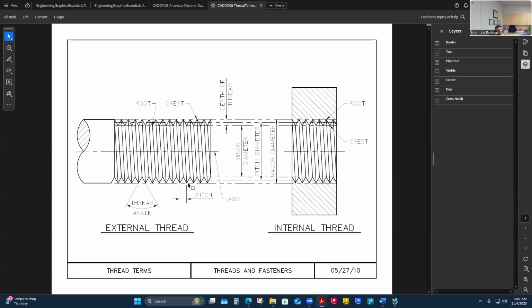The reason why I might need to know this is if I'm looking to design a round fastener, or if I'm redesigning something and I've got some equipment that I'm working with, I need to identify what the fasteners are that are being used so I don't detail them out wrong. So I might have to grab a fastener, grab my calipers, and do some measurements to determine what it is that I'm going to call out in my print, right? So that's a common reason why I have to nerd out over this stuff, to be able to identify fasteners off a table or something.